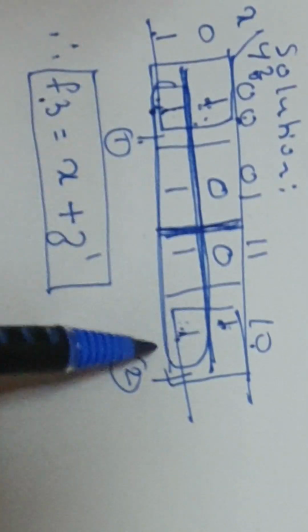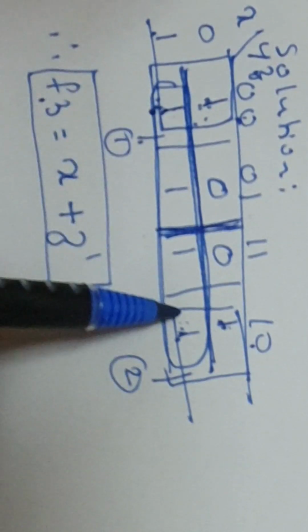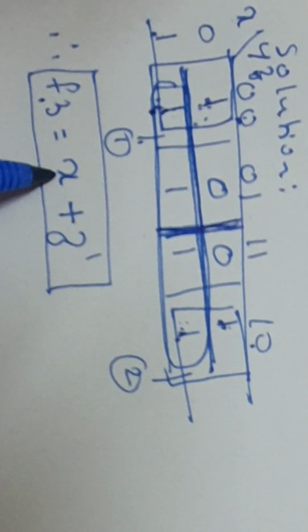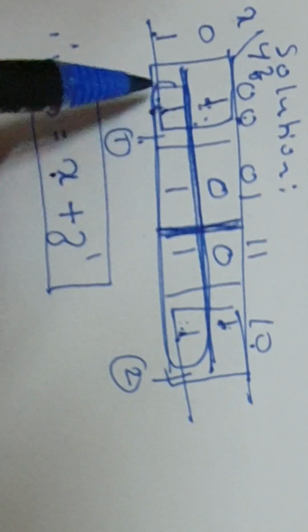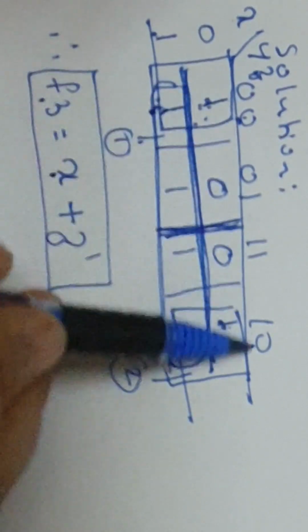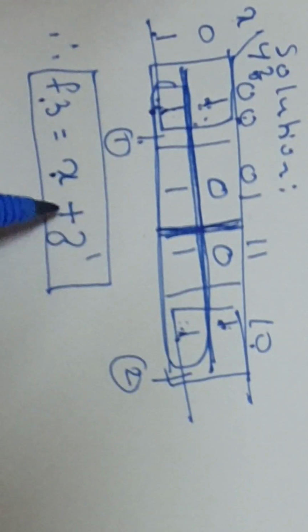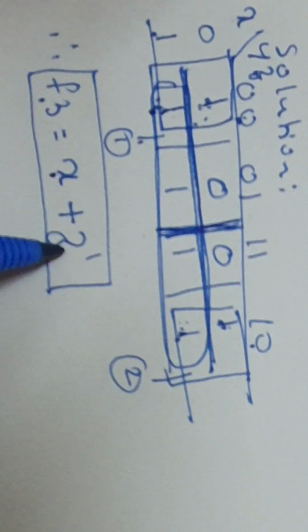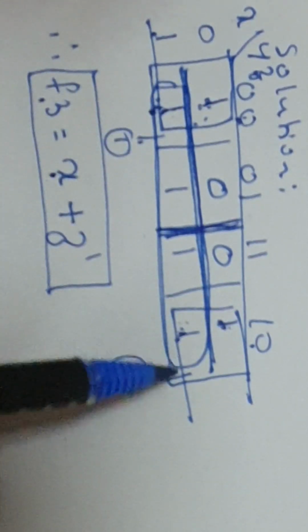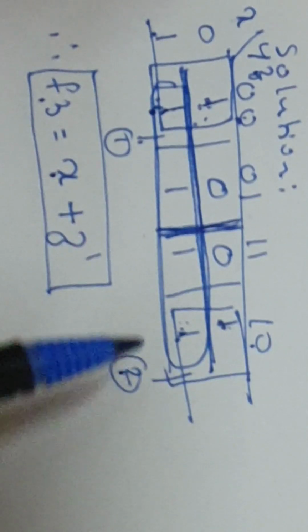With respect to the first group, all 4 ones are in one row, so x is 1, which means x is common here. Column wise, all 4 ones come in 4 columns, nothing is common here, so leave that. Then go to the second group. These two ones form the second group, that is a quad.